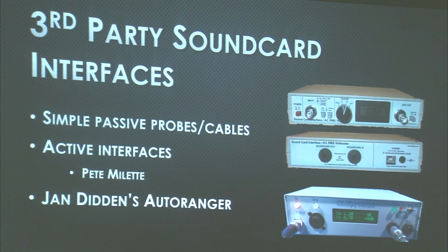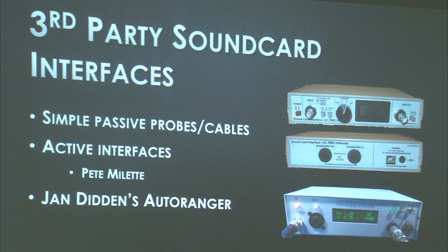Okay, and now this goes back to using those sound cards to measure audio. If you take one of those standard sound cards, any of the ones that I've shown there, or for example, Focusrite or one of the EMU USB cards, the problem is their input range doesn't match testing audio products. If you're just testing line level stuff, fine, but if you're actually testing an amplifier, it won't work. You'll break something. You can build a simple passive interface. It's finite, you know what it is, but you know, it's kind of kludgy.